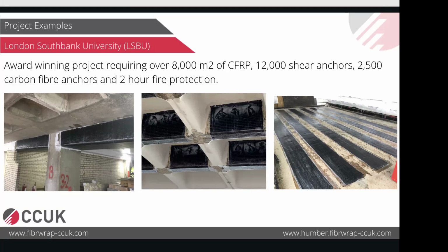The reason for the strengthening was that they were remodeling the university. They were changing the position of the library from one area to another, introducing a new stair core and everything. For that reason, these traditional 1960s waffle floor slabs needed strengthening. Structurally, for some bizarre reason, there is no reinforcement in these transverse ribs, so it was treated as a one-way spanning rib slab. For that reason, we treated it as T-beams, or a row of T-beams.